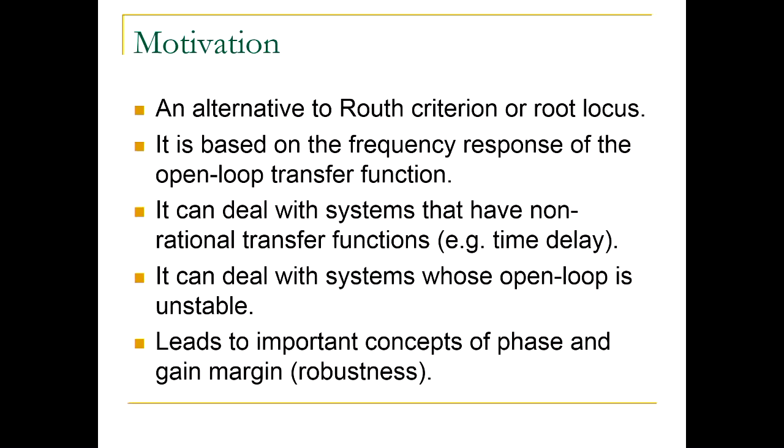So why do we do Nyquist? Well, first, it's an alternative test, an alternative way to check stability. It is based on the frequency response of the system, and we saw that for stable systems we can experimentally determine frequency response. It can also deal with systems that have time delays.